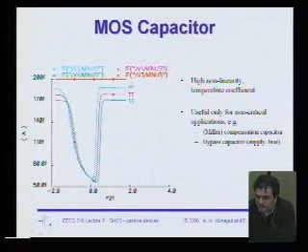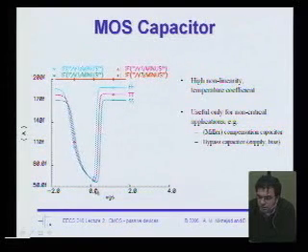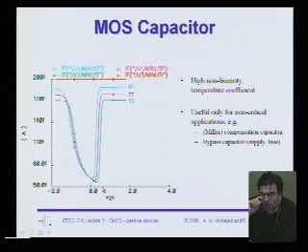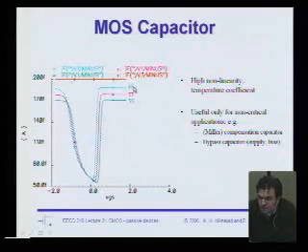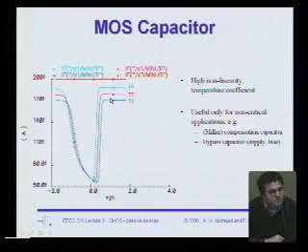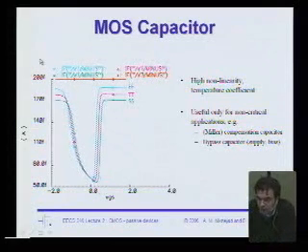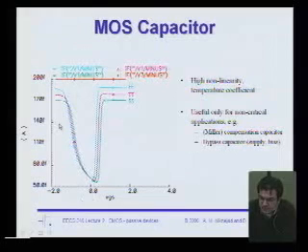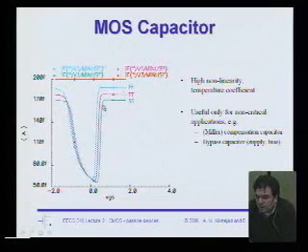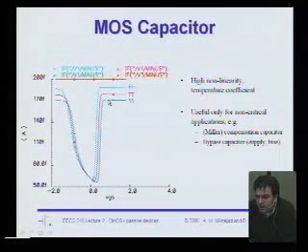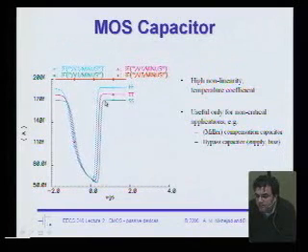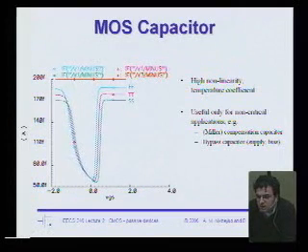And then I plot the same thing, the current going into my capacitor, and you can see, again, this huge variation from this point to this point. You can see the capacitance changes almost 3 to 1. This is, again, that exponential increase in charge, which leads to this great change in capacitance. Over here, it's more gradual because of the depletion effect, right? So this part of the curve is much more gradual than this part of the curve. If you look very carefully, you'll see that this curve actually is going downwards, right? In fact, the capacitance is decreasing as we increase the voltage, right?